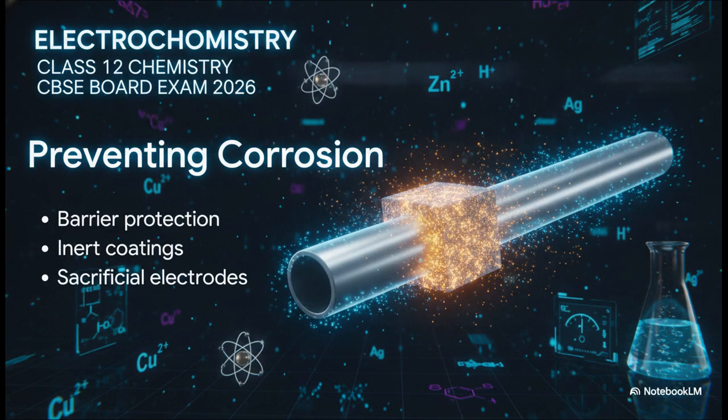But luckily, electrochemistry also provides the cure. We can use barrier protection like paint or an inert coating of zinc or tin. But for sure, the most fascinating method is the use of sacrificial electrodes. We can intentionally attach a much more highly reactive metal like magnesium right onto our iron structure. The magnesium essentially sacrifices itself. It corrodes away entirely, so the structural iron stays completely protected. It's a seriously ingenious electrochemical trick to save our buildings and bridges.